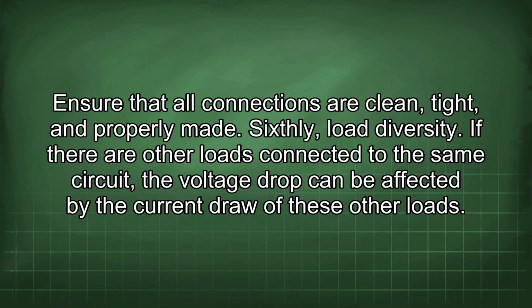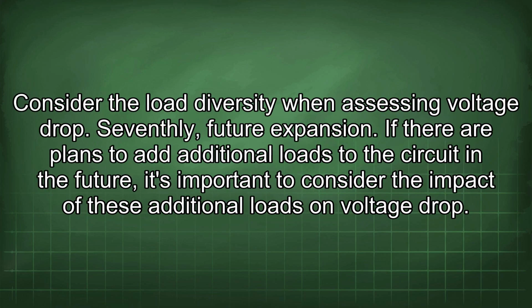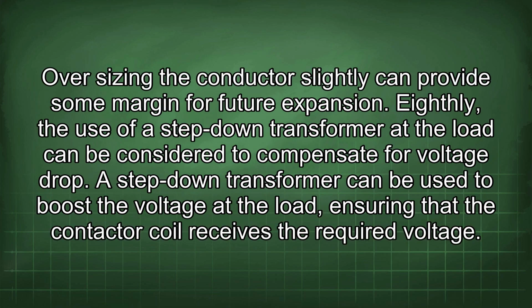Sixthly, load diversity. If there are other loads connected to the same circuit, the voltage drop can be affected by the current draw of these other loads. Consider the load diversity when assessing voltage drop. Seventhly, future expansion. If there are plans to add additional loads to the circuit in the future, it's important to consider the impact of these additional loads on voltage drop. Oversizing the conductor slightly can provide some margin for future expansion.